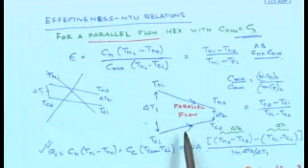And since it's a parallel flow simple 1-1 heat exchanger, no correction factor to LMTD needs to be provided. So whatever LMTD we calculate based on the inlet temperature difference and the outlet temperature difference can simply be used to express the total heat transfer in the form of Q equals UA delta T LM, where U is the overall heat transfer coefficient. The overall heat transfer coefficient consists of the convective resistance at the inside of the tube, the convective resistance at the outside of the tube, and the conductive resistance of the pipe wall if the pipe is not thin. So if the pipe is thin, the overall heat transfer coefficient has two components.